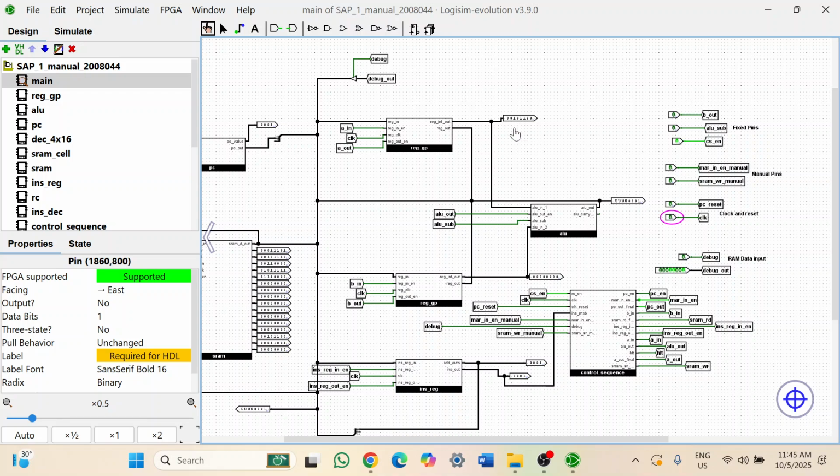We can see that the binary value of 44 is getting saved in register A. So for the next 6 clock pulses, the binary value of 25 will get stored in register B. So we are going to give the next 6 clock pulses. We can see the binary value of 25 showing in register B.